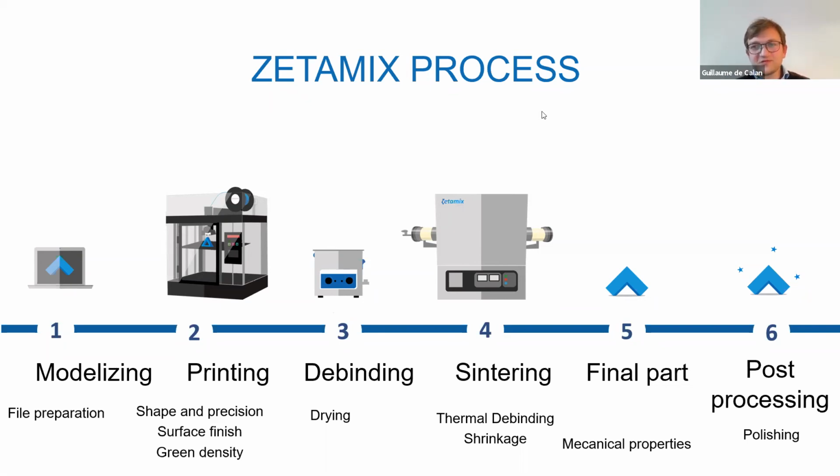Does removal of support potentially initiate cracks in ceramic after sintering? For those who know ceramic, potentially anything can initiate cracks. Ceramics are brittle materials, so during sintering, there's always this question, which is not easy, about how to avoid any cracks.